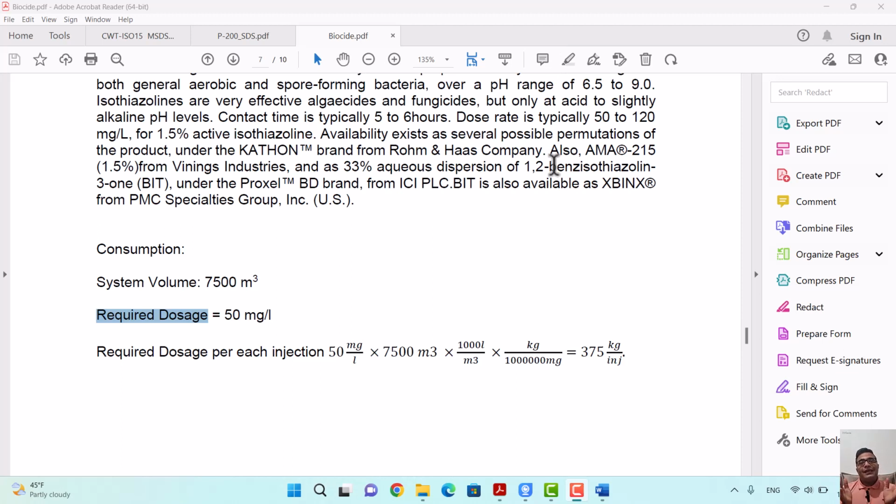Sometimes your cooling water system demands that the non-oxidizing biocides be injected weekly, but sometimes on a 2 week basis. For my systems, if I inject on a 2 week basis, it is enough. Everything is clean, and everything is on the safe side.